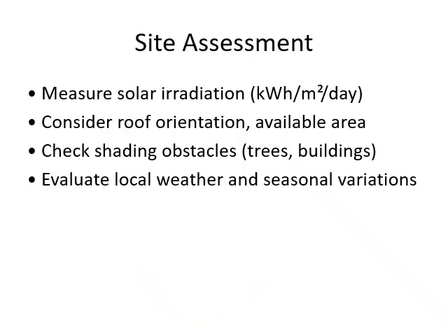Then comes the site assessment. We have to measure the solar irradiation, and another important thing is we have to know for how long we are having the full sun. Remember the solar peak hour, we learned in lecture 2 or 3. So we need to know how many hours we are getting the sun, and also the kilowatt hour per meter square per day. We have all learned these measuring methods at the beginning.